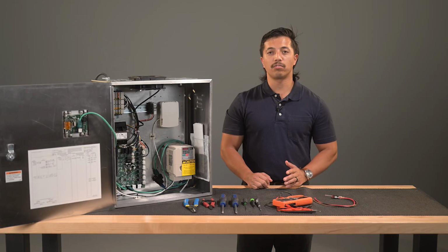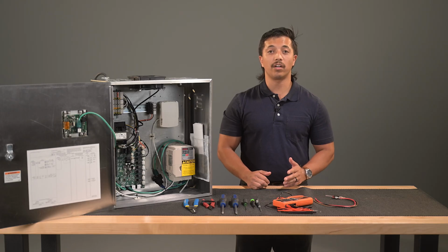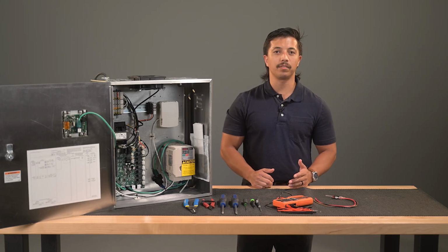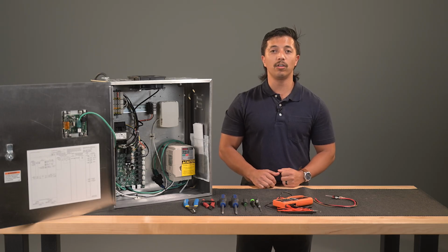These contacts are dry relay contacts and have no voltage or power from the factory. They are best described as a switch that our board controls in fire operation. Dry fire contacts are typically used for shunt trip breakers or contactors in order to kill power to the appliances underneath the hood. The contacts are rated for 8 amps and 250 volts AC.